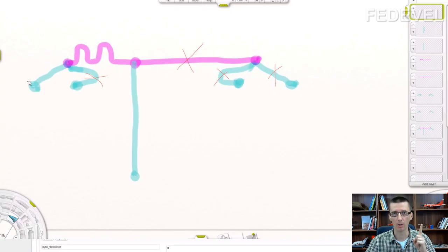Be very careful. The only part of the tracks where you can draw the waves is this one here. So you can draw the waves here to do the length matching for all the signals in this command control address group. Do not draw waves here, do not draw waves here. Why? Because then you break the balance between these segments here. Only draw the waves here. Have a look at a real example.